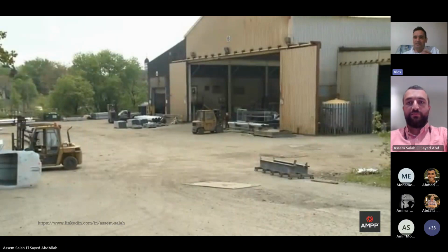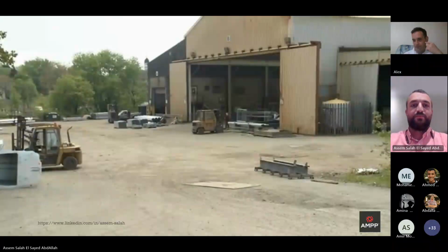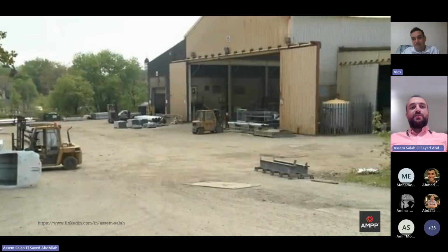I mean, effective. But at the same time, first of all, keep in mind that you are limited by the dimensions of this galvanizing bath. So big details, big structures are not subject to use this sort of protection. Yes, because only maybe small pipes or small bars or lighting bulbs, I think. Lighting bulbs, and even small structures. Even in Egypt, you don't have many companies which use this technology.